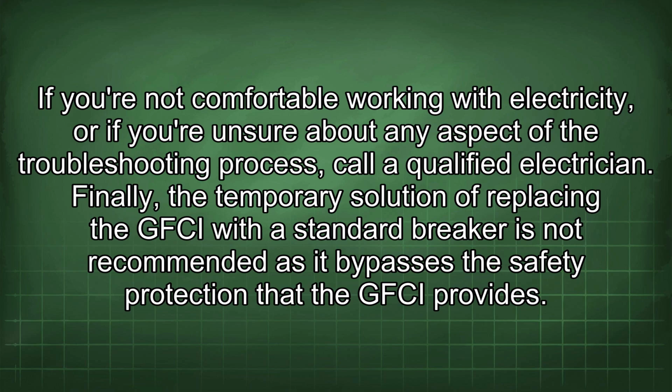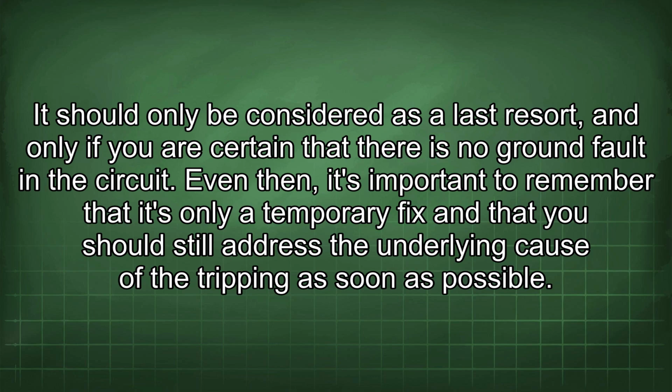Finally, the temporary solution of replacing the GFCI with a standard breaker is not recommended, as it bypasses the safety protection that the GFCI provides. It should only be considered as a last resort, and only if you are certain that there is no ground fault in the circuit. Even then, it's important to remember that it's only a temporary fix and that you should still address the underlying cause of the tripping as soon as possible.